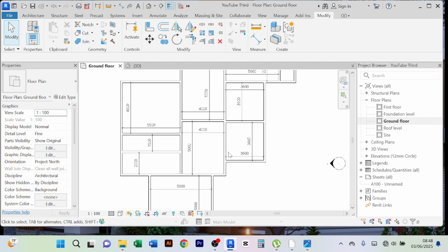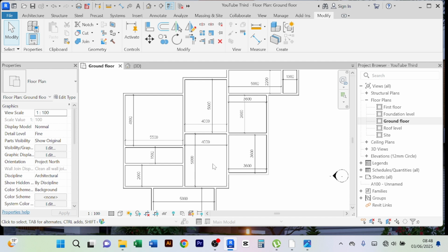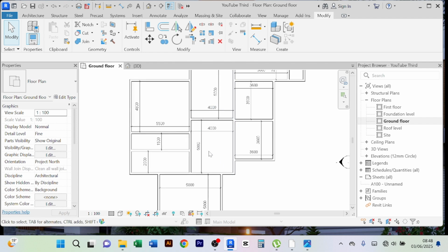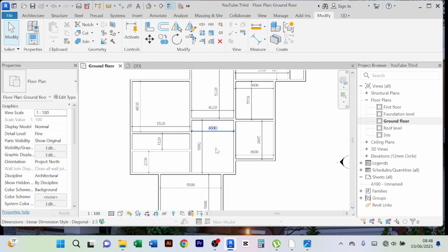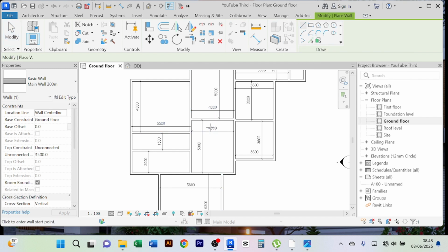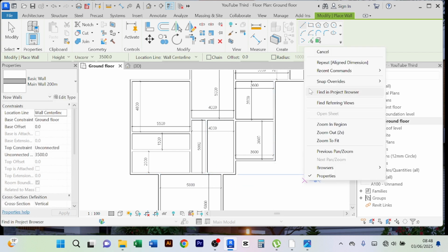We are going to make use of this space with this bedroom here. We shall extend this bedroom a little bit inside, right? So I'll extend it a little bit inside, maybe here to leave a small corridor to go to the dining, things like that. Let's say we are creating a wall here. You can create a similar wall. You just click on any wall, you come to our create similar. You remember it? I hope you do. So you create a wall here.